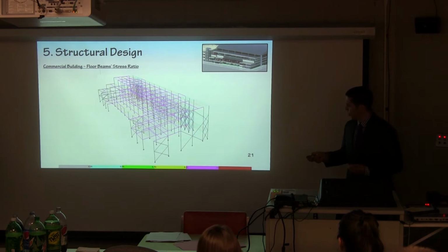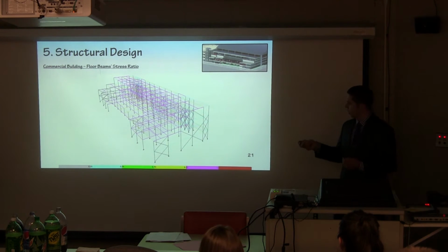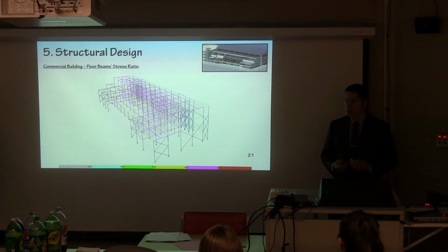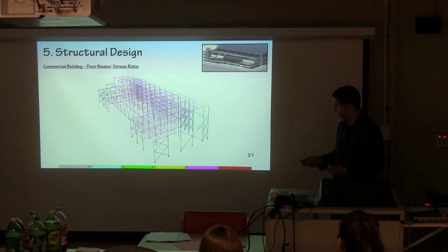Here, as I said earlier, is the southeast portion. But you can see here, as Gerard said, the members here are much understressed, and that's due to the serviceability and the deflection requirements through AISC.